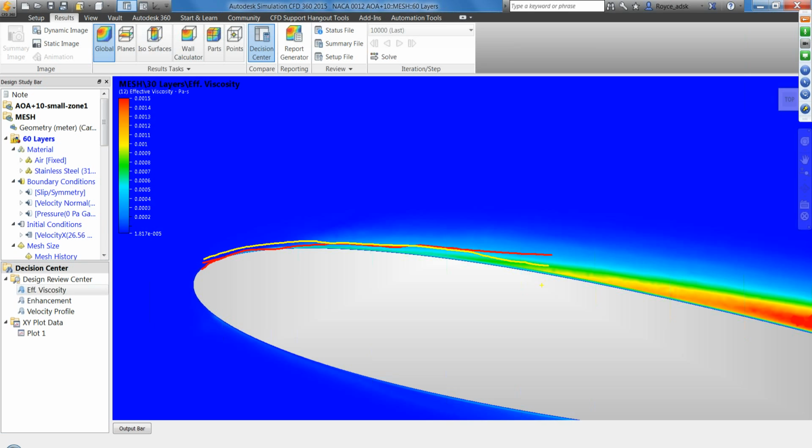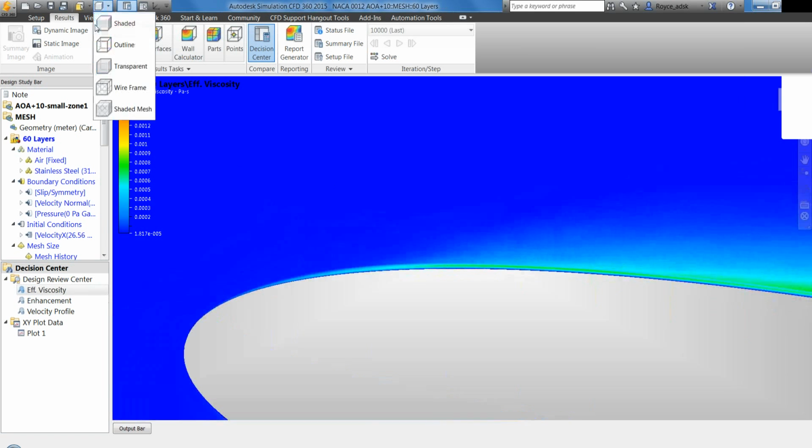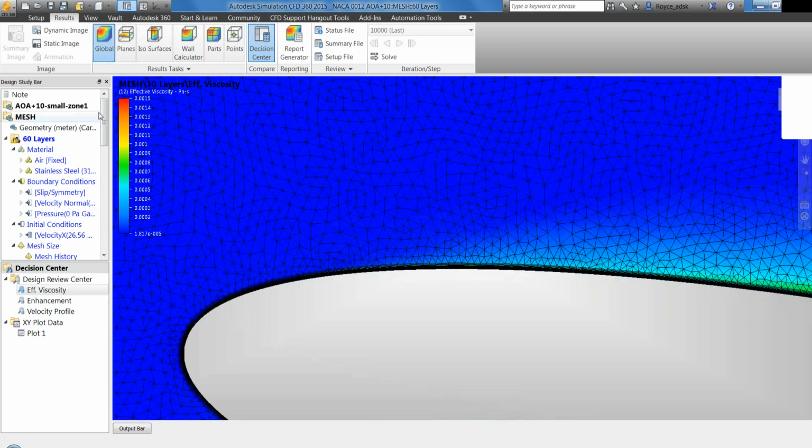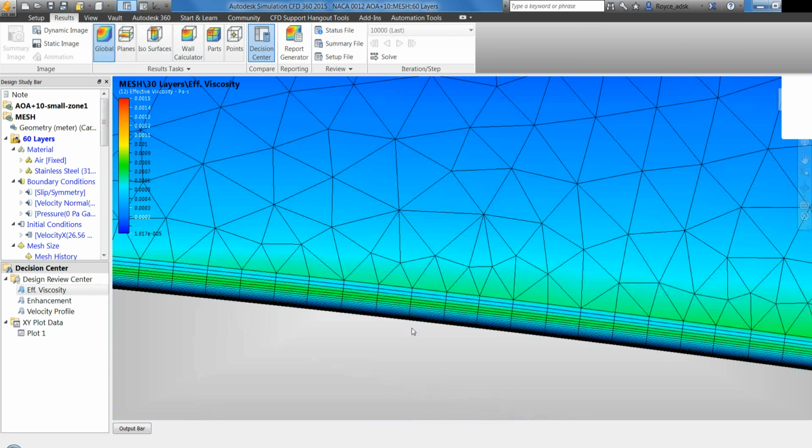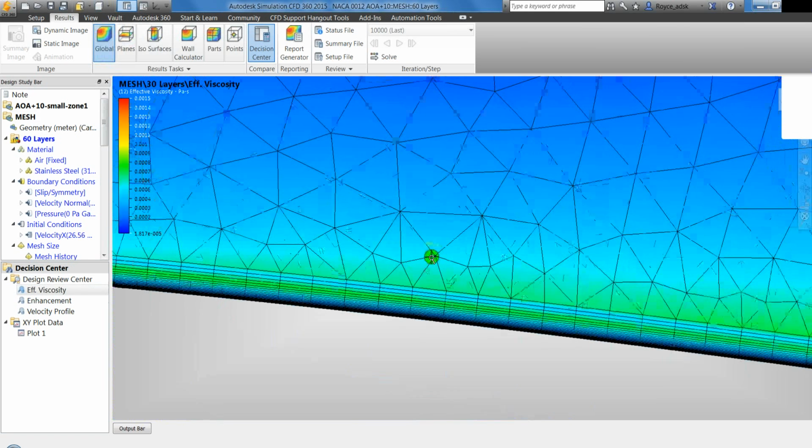Okay. From there, the mesh enhancement elements to the core elements, there's structural differences, but really the equations that are being solved are exactly the same. So as long as you have a clean transition from your wall elements all the way into your external flow, then that's what you really need to make sure you do.